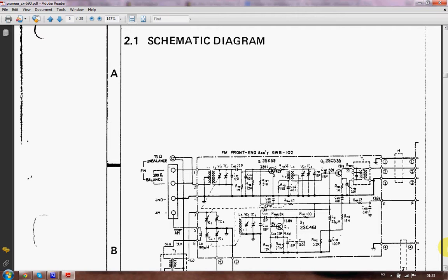And whenever we're talking about a signal, we're talking about alternating current if we're talking about an analog signal, naturally generated and not rectified or semi-rectified. It's going to be alternating current. Just to explain a little bit about it, a capacitor will always block direct current. So if a capacitor is in the series of a direct current circuit, it's going to break the circuit. It's like an open circuit if a capacitor is in the series somewhere.